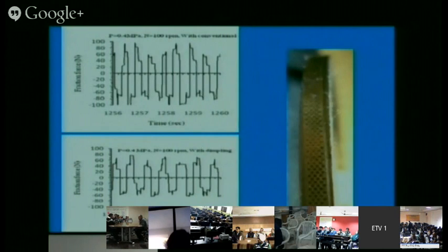When a single profile has been modified, under the same operating condition, we get roughly 70 or 80 Newton. So we can say about 20% reduction in friction takes place merely by modifying the profile of a single piston ring, not all.